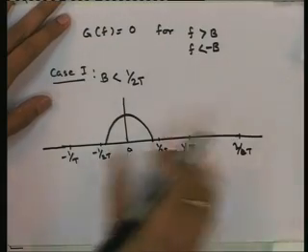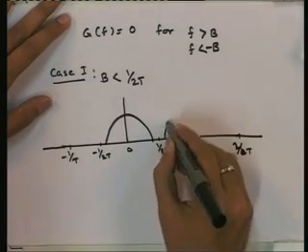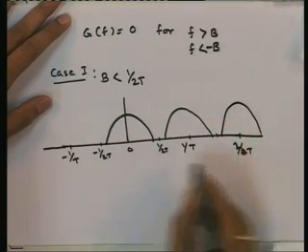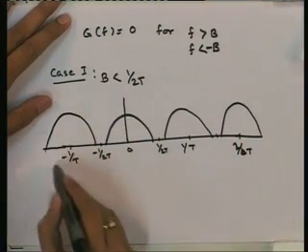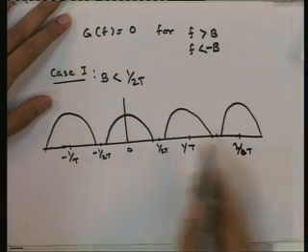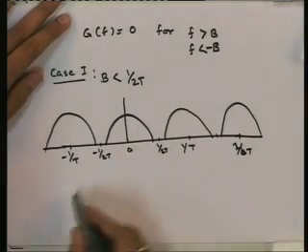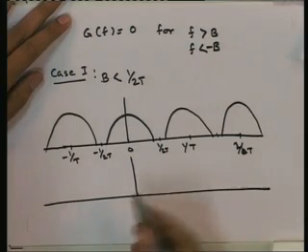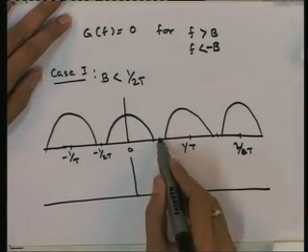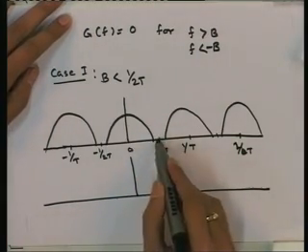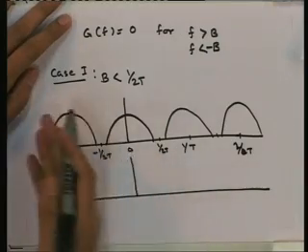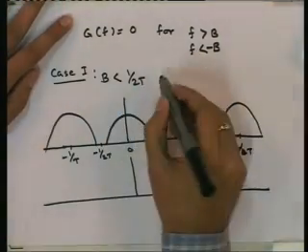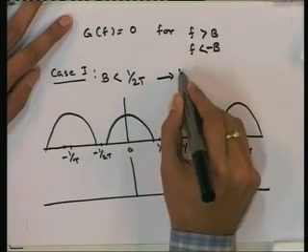So when we shift it to 1 by T, what do we get? We get this. Similarly, we get it on this side. So when we add this, are we going to get amplitude 1 everywhere? We are never going to get it, because here there is nothing, so the value here will be 0. The addition is basically this, so it is not constant 1. So in this case it is impossible to have 0 ISI.